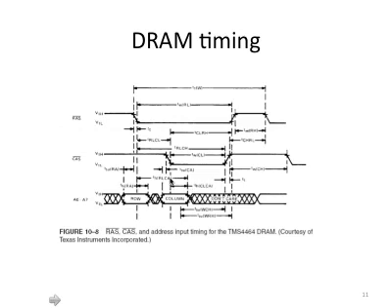And after a certain time, the control circuit puts the column address on this 8-bit address bus, and then asserts, which means it turns the column address strobe from 1 to 0 to indicate that currently this is a column address.